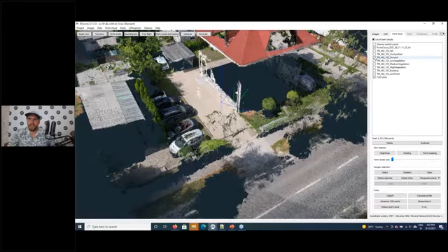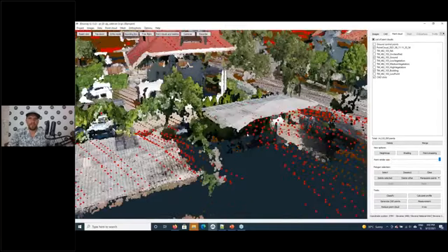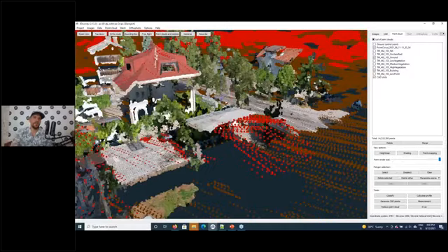Turn on the ground and building layers. Increase the point size so that we can see them. Because the difference is systematic, we know that probably either our GPS or their GPS showed a slightly different value. Also, this LiDAR data is now maybe 7 years old, so back then maybe they applied another geoid model, because of course it gets updated, and when they update it, it changes by a little bit.